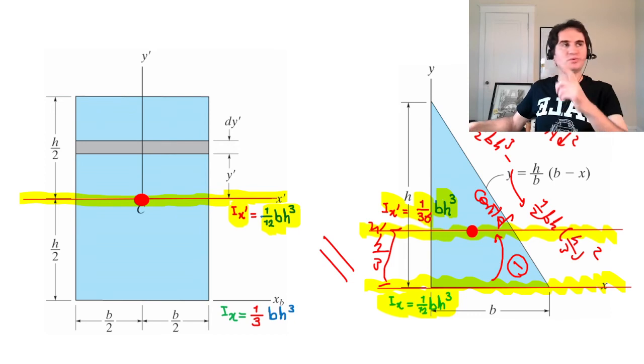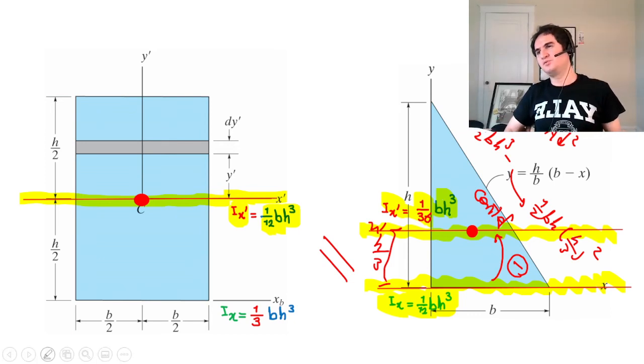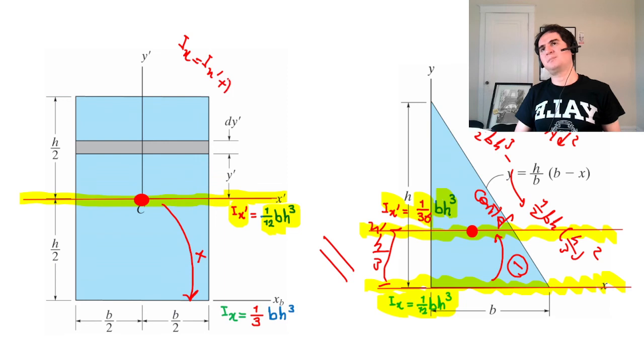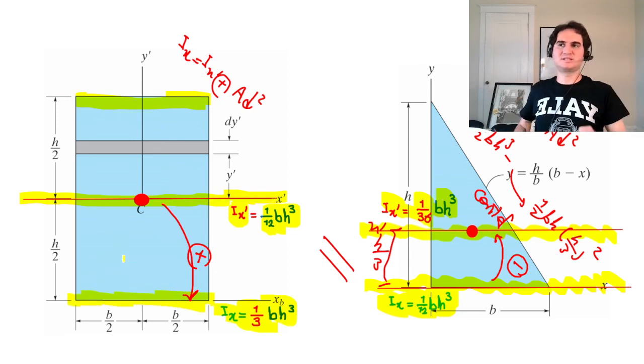And you can apply the same concept if you want to travel from the center to any other axis. That's a plus. And that's Ix. In those terms, it's Ix prime, the centroid, this time plus. I'm going out, it's a plus A d squared. If you do the math, it gives you Ix is one third of base cube height for the sides. For the center it's one twelfth, for the sides it's one third. You can easily see how it increases.